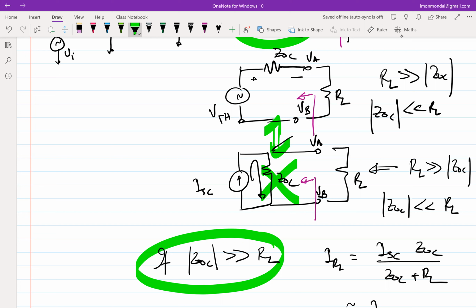That's what it means, right? What is a drop across its terminal? What do I mean by a drop across its terminal? It means that its output impedance is not zero, right? Nothing will be zero. It will be some finite, but that finite has to be much lesser than what you want. What you want is ultimately the battery voltage to appear, right? So you don't want any loss. The loss is equivalent to the drop.